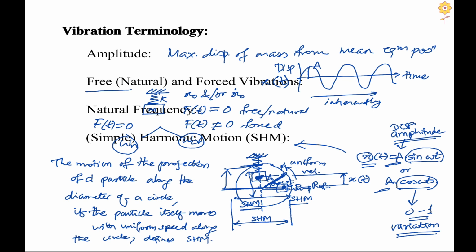Okay. So, for the second definition, we have to refer to this equation, right? X of t is equal to a sin of omega t. Now, suppose I take the derivatives of this with respect to time. I am having here omega a cos of omega t. So, in this case omega a separates the cos term. So, cos gives us the variation, omega a is the amplitude for velocity, it is the maximum velocity in that cycle.